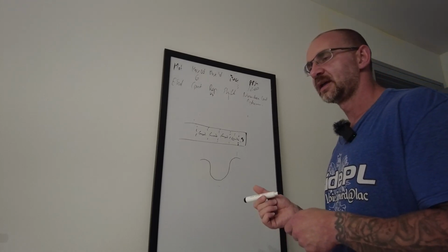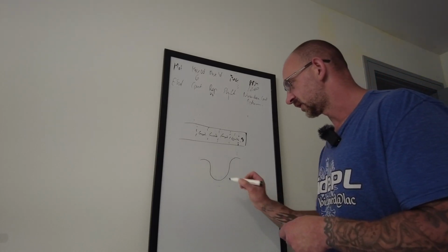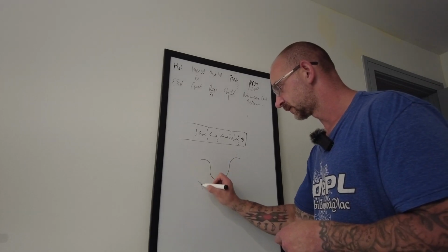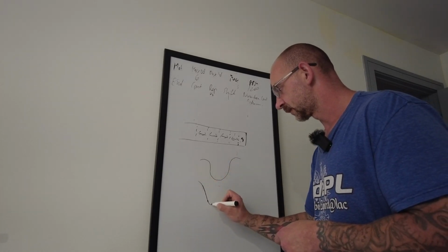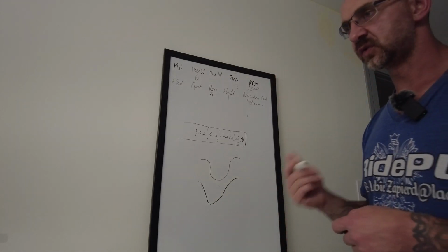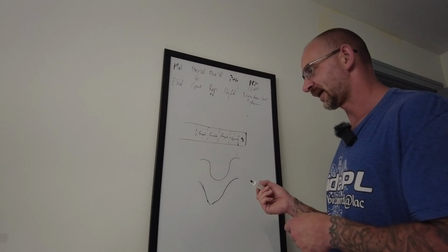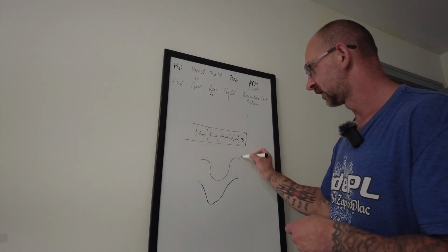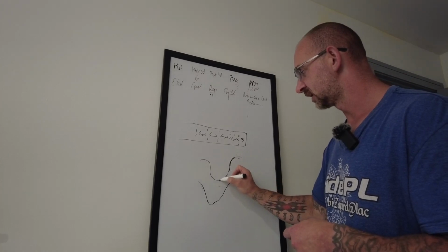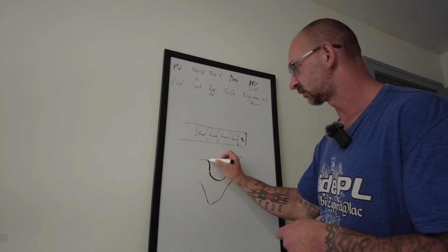If you program it as a groove and you throw in big radiuses here and there, sometimes it just can't read it. So in situations like that, I'll have to come in with the OD turning tool and create a radius into a radius, into a radius, into a radius.